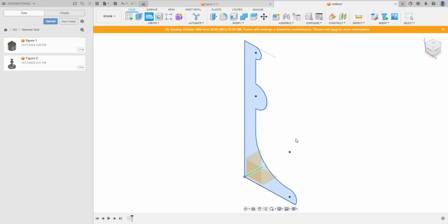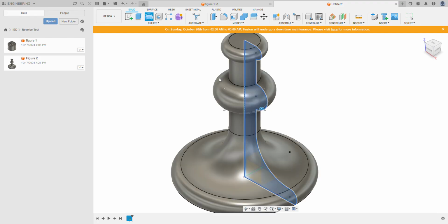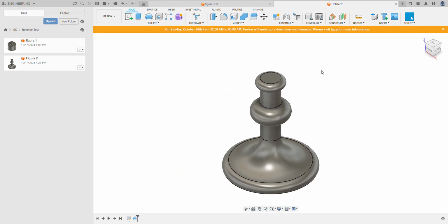But in our case, we want a candle wick where the center line is this very long one. I'm just clicking those just so you guys can see. Nope, so it's not any straight line, but you can click on any and it can change the general shape. That being said, our candle wick is rotated or spun around this line. And you just press OK and we're done.